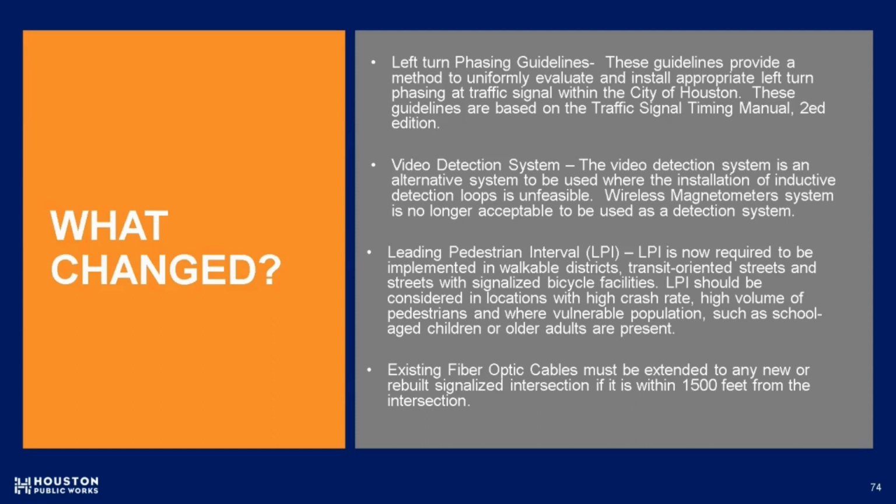The City of Houston is reintroducing the video detection, also known as VIVIDs, to replace the wireless magnetometers. We have about 400 signalized intersections where we implemented wireless magnetometers, and we're having some issues with them. The technology did not really deliver what it had promised. We have experienced several issues, such as failing batteries, lack of accuracy in volume and occupancy counts, and other issues such as interference and signal strength.